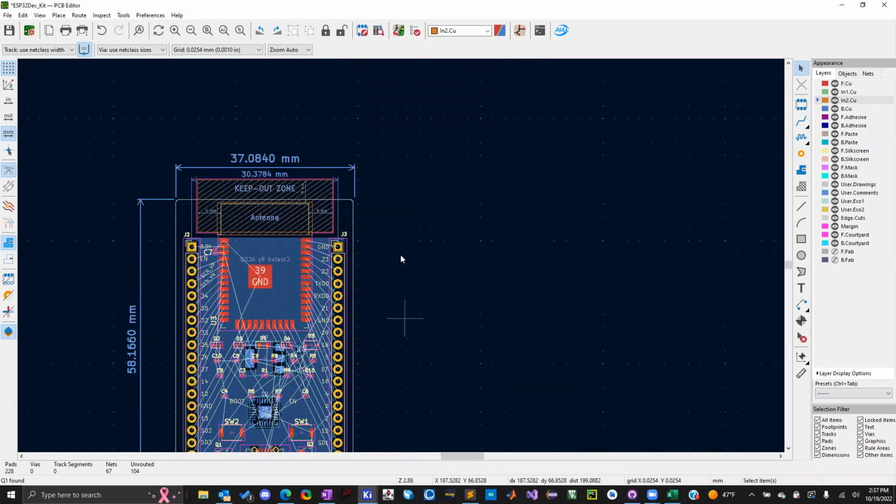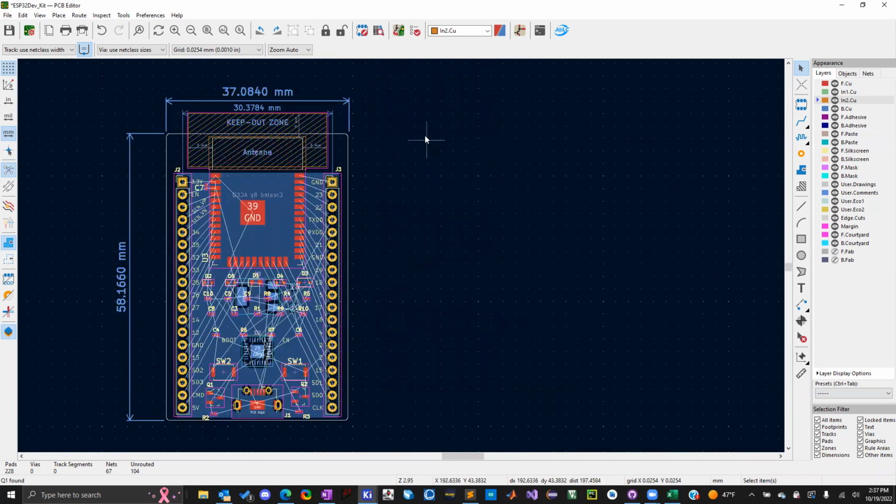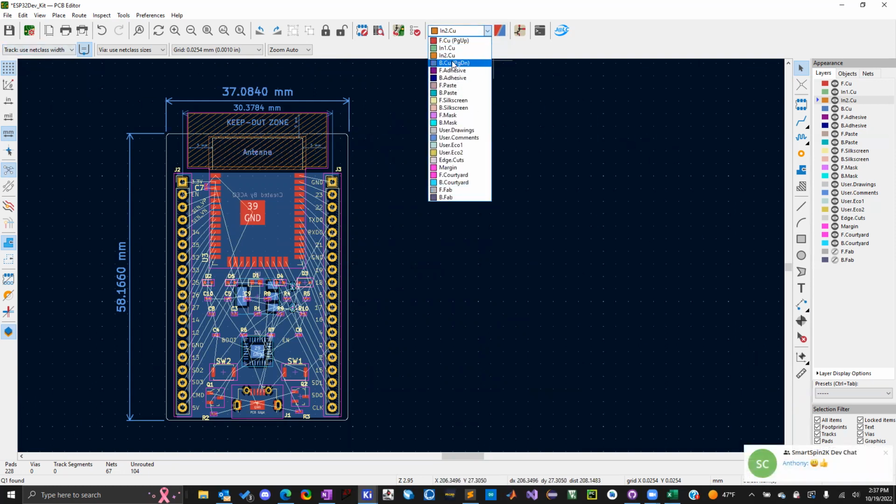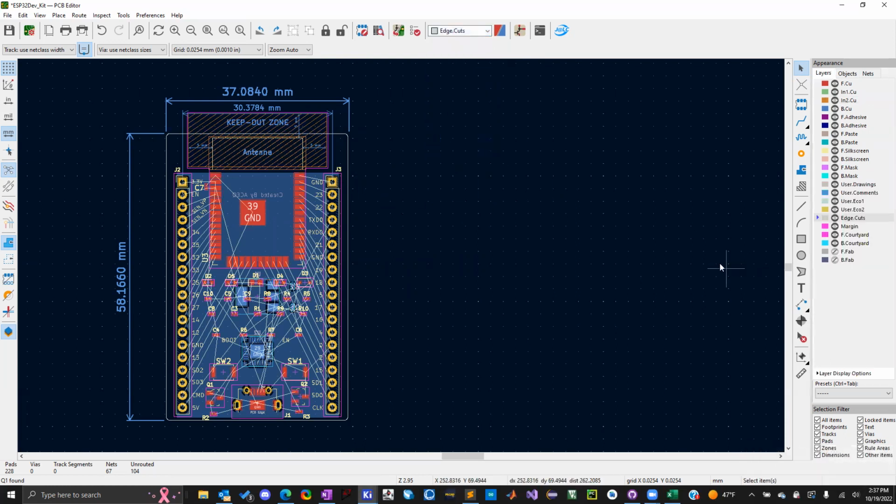The first thing I would do, I guess, is place your components out to the side and go ahead and just start making your edge cut. So we're going to make the layout of the board. Let's do it on front. There it is, edge cuts. I don't know why I couldn't find that. Go ahead and click on the draw a rectangle.